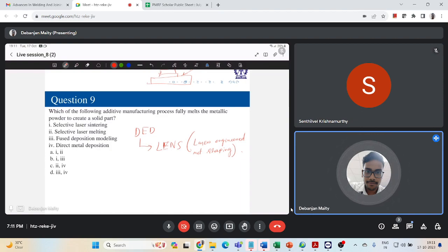The advantage of DED printers is the ability to produce large part volumes or for repair purposes. You can repair damaged parts by using them as a substrate or build plate, in contrast to the powder bed fusion system. Also, the DED system offers you more flexibility in terms of heat source and feedstock. You can use laser, arc, or electron beam as the heat source, whatever you want. Metal wire or powder can be used as the feedstock. Those things we have already talked about.